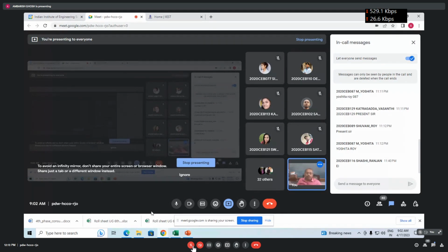So small k1 you have got 9 into 10 to the power 3. Then E is 5,000 into root over fck. Then your I is pi d to the power 4 by 64. From K1 you can calculate capital K. Now you calculate R equal to 4th root of EI by KB.